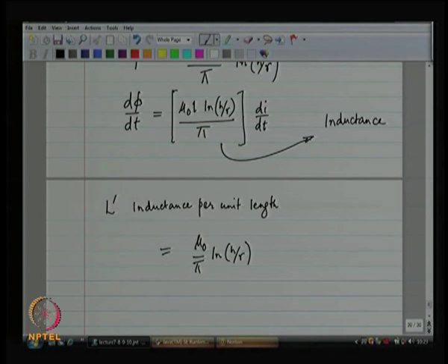Okay. So, there have been a lot of simplifying assumptions in this derivation. However, what I need you to understand from this is that even a wire has some inductance per unit length. Longer the wire, more the inductance, right. Also, more the separation between the wire and its return path, more the inductance. Okay. So, things will change if you change the geometry.